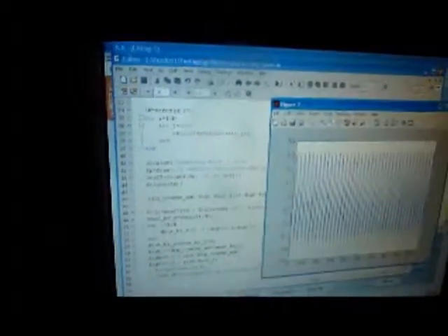So to take it into MATLAB, we just use it in the listing mode, and then we go for file and export the data. And we save it as a text file as shown above, listing space 108.txt. This is then processed in MATLAB, and this shows the MATLAB code which captures the data. It is shown that it is reading the file listing-108.txt and then processing it, and then finally it plots the output of the overall ADC output,